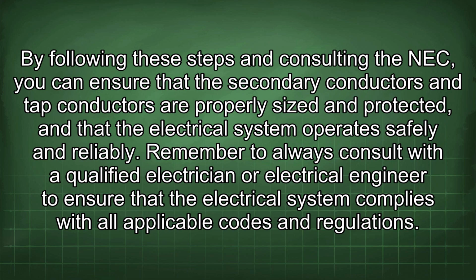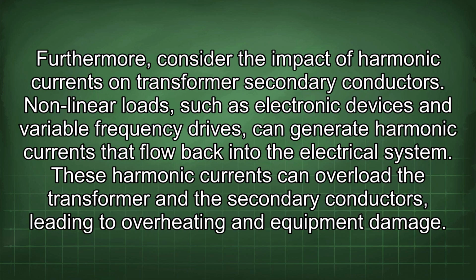Remember to always consult with a qualified electrician or electrical engineer to ensure that the electrical system complies with all applicable codes and regulations. Furthermore, consider the impact of harmonic currents on transformer secondary conductors. Nonlinear loads, such as electronic devices and variable frequency drives, can generate harmonic currents that flow back into the electrical system. These harmonic currents can overload the transformer and the secondary conductors, leading to overheating and equipment damage.